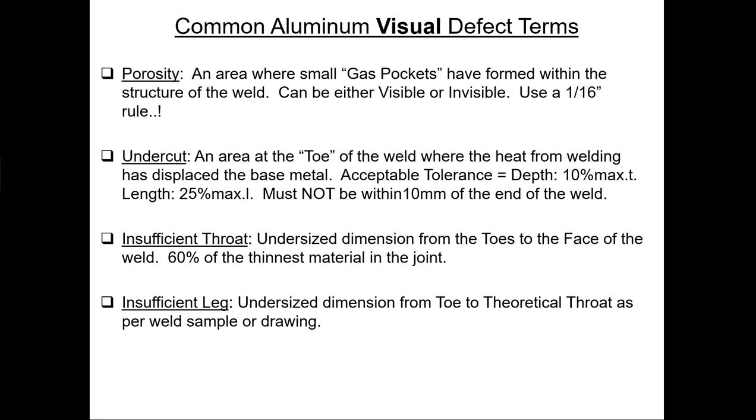Most specifications say if a hole is visible and it's 1/16 of an inch or larger, that's immediately a repair. We'll talk about the repair procedure in a little bit. Undercut, I have good examples of undercut coming up. Basically, the material's been washed away a little bit.